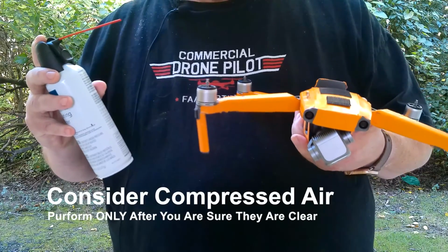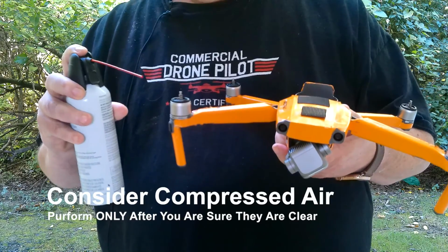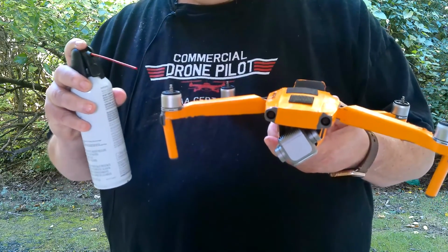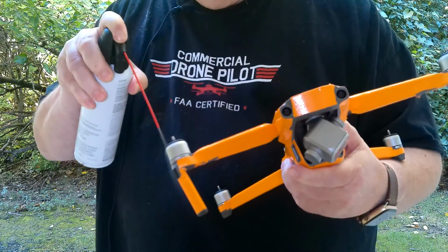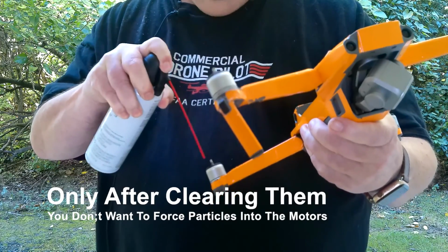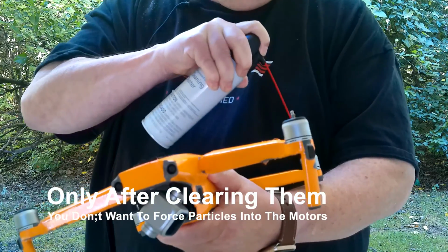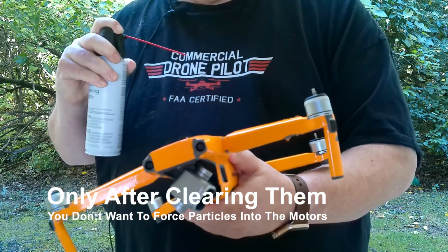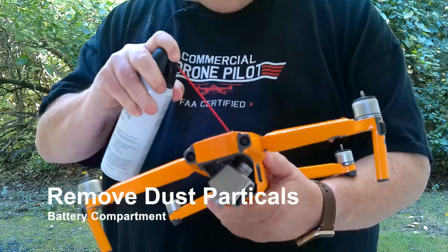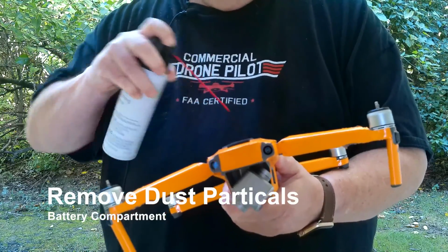It's always a good idea to have a can of compressed air handy that you can use to help keep the drone clean and free of debris. You want to blow out each of the motor housings and just make sure there's no dust or anything else that can start to build up and impair their function. You can blow out your battery compartment and the connections. Make sure that stays clean.